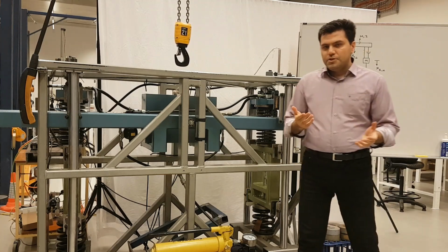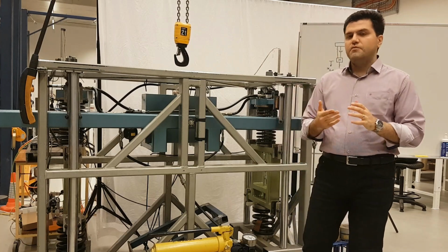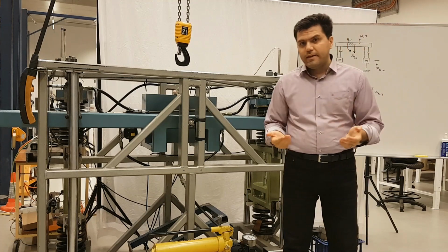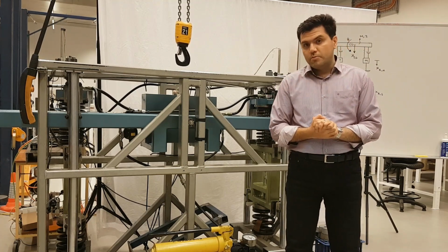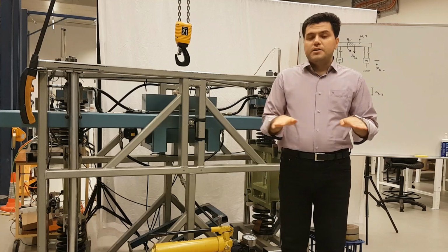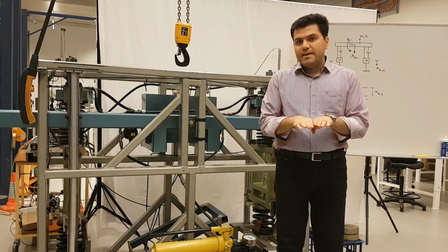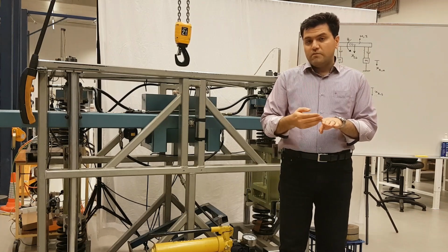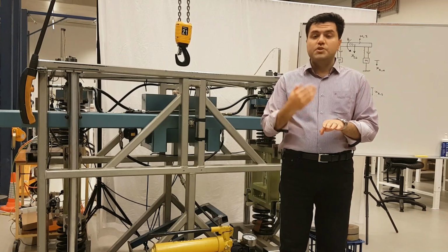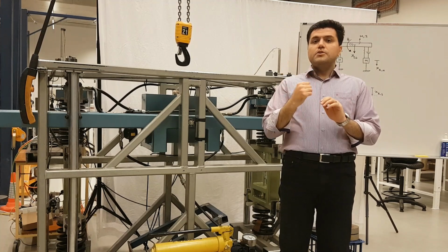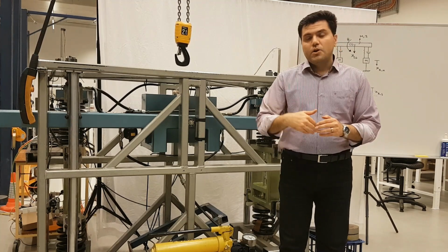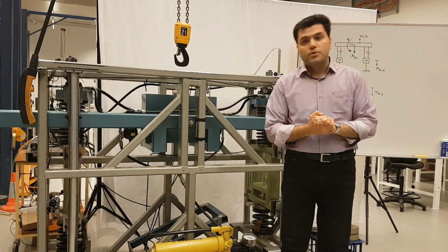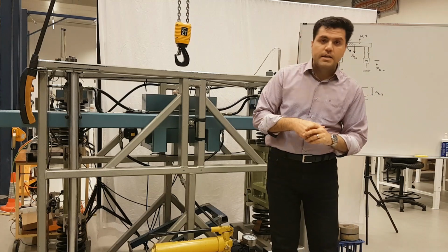You know that in reality, if you model a vehicle as a rigid plate, generally speaking, it has 3 modes of vibration. The bounce mode. Another mode of vibration is called pitch mode, which is front to rear or rear to front. And another mode is left to right or right to left, which we call roll mode.